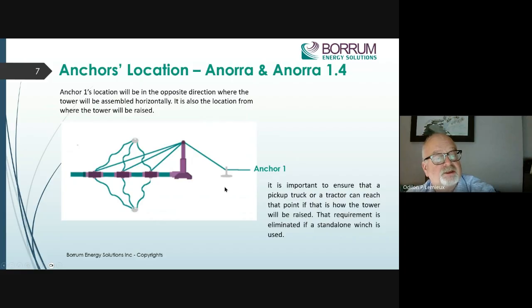So here's the thing. If you're planning to use a pickup truck or a tractor, then you want to make sure there's enough room on this side to bring your tractor or pickup truck there to raise the tower. Sometimes people forget about the room required for that. If you're going to use a winch, it may not be that critical. You can use the anchor itself to connect to the winch, or other items like a tree or something like that.